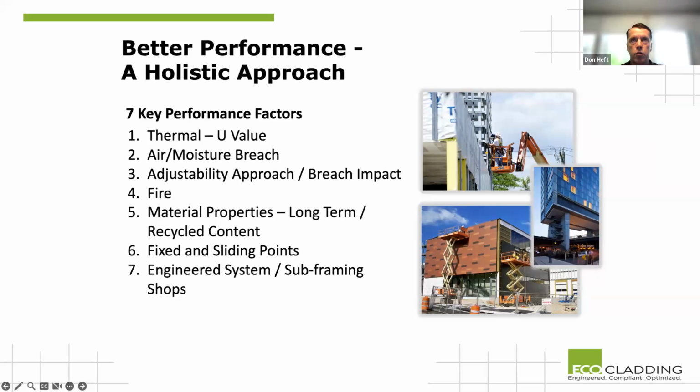That's a standard approach for us, to do thermal modeling for all of the projects that we're looking at. And as we're penetrating the insulation layer, we're also having to go through the air and moisture barrier on that side of it. So we minimize what happens there and what that looks like at that penetration point. And then also giving an adjustment of the system. I'll show in a later slide that each of our systems has an internal adjustability, so it minimizes or eliminates the need for shimming these systems. That helps with water penetration issues that you may have, and also helps the installer get this on the wall and work with a nice flat wall.